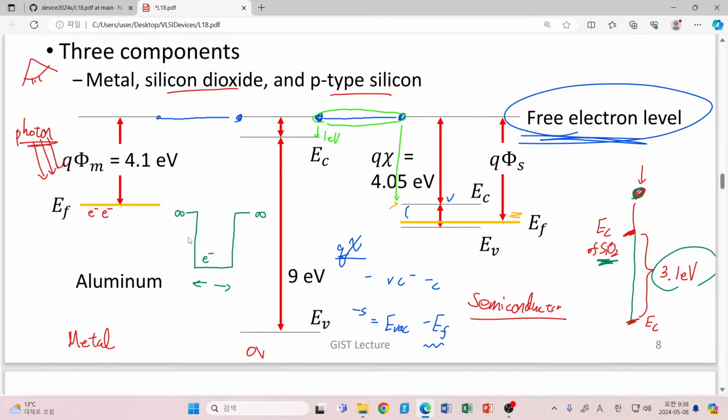And please note that our usual energy scale is just milli electron volt. You know, we are much interested in small changes in voltage because our formula changes with the scale of 1 thermal energy, 2 thermal energy, 3 thermal energy. So this 3.1 electron volt corresponds to roughly 112 times our thermal energy. So it can be regarded as a really tall barrier.